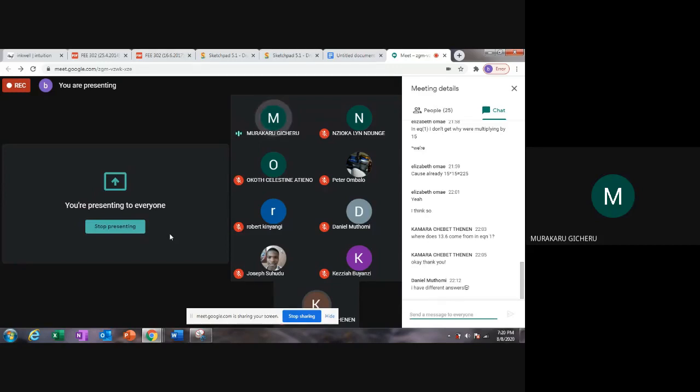Because when we're considering ICQ in the class A amplifier, it's because we're using a collector current value that comes, quote unquote, from the DC source. When we want to find ICQ, it's a DC current, so we draw the DC equivalent to solve for it.